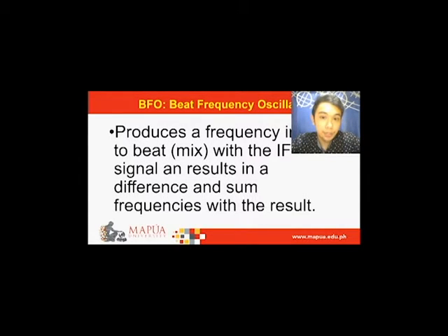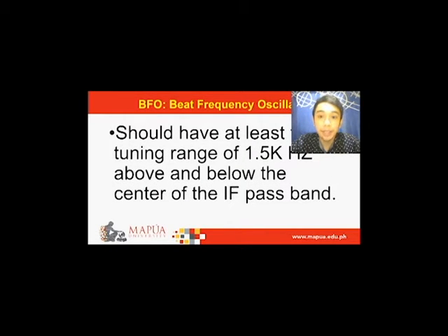So what is the BFO according to the book? It is to produce a frequency input to beat or mix with the IF signal and result in a difference frequency. It should have at least a tuning range of 1.5 kHz above and below the center of the IF passband.